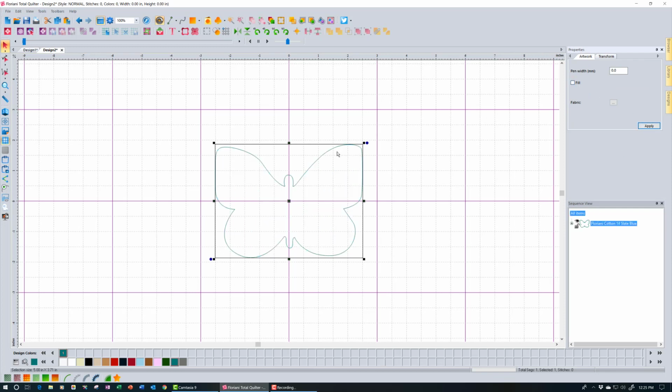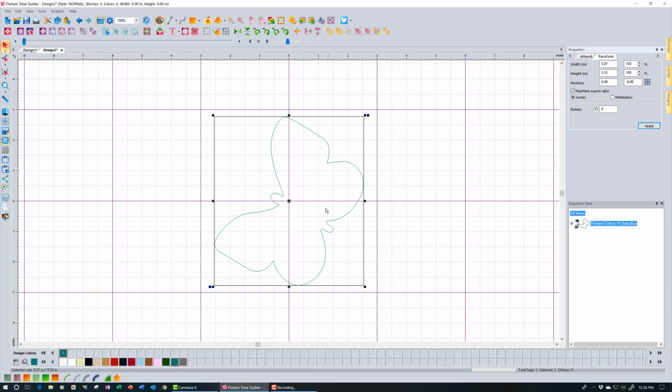And then same thing applies. If I wanted to go straight across with my chenille stitches, I could just do the chenille stitches now, but I can also rotate this butterfly to any degree I want. So let's say I wanted to do 60 degrees, I click apply, and then I can see that my lines are going across, and I would just draw in those lines. And I can see my grid. It looks pretty darn good for the edges here just by happenstance. So I would draw all these lines in.